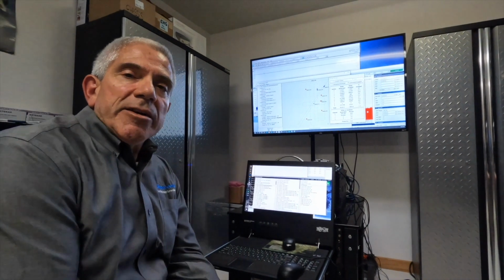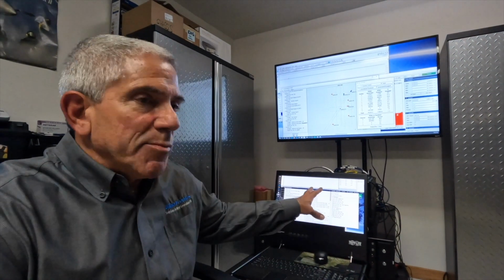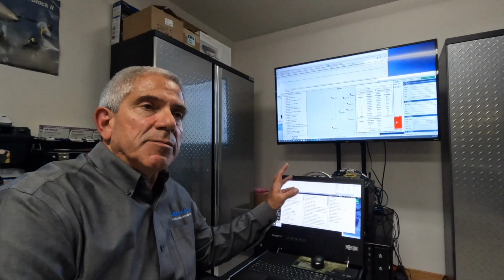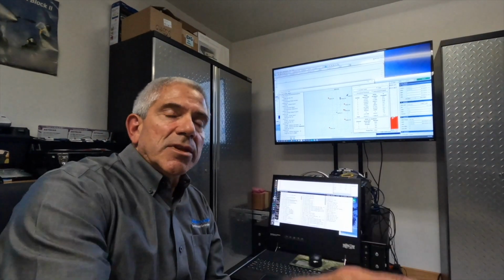That intermediate IF frequency is actually at 1200 megahertz with a full 1 gigahertz of instantaneous bandwidth. And what we'll do is we're actually going to cable the output of that RF system at the IF pulses into the capture system and show you what that looks like.